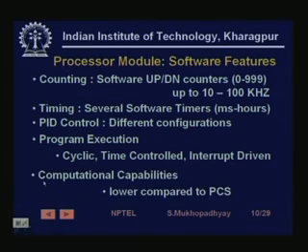But all said and done, one must understand that typically a PLC has much less computational capability compared to a PC, although it is generally much more expensive. That is, if you take PLCs and PCs of the same kind of price, then you would find that the PLC is much less computationally capable compared to a normal PC which sells in the market, both in terms of memory and in terms of computing speeds.